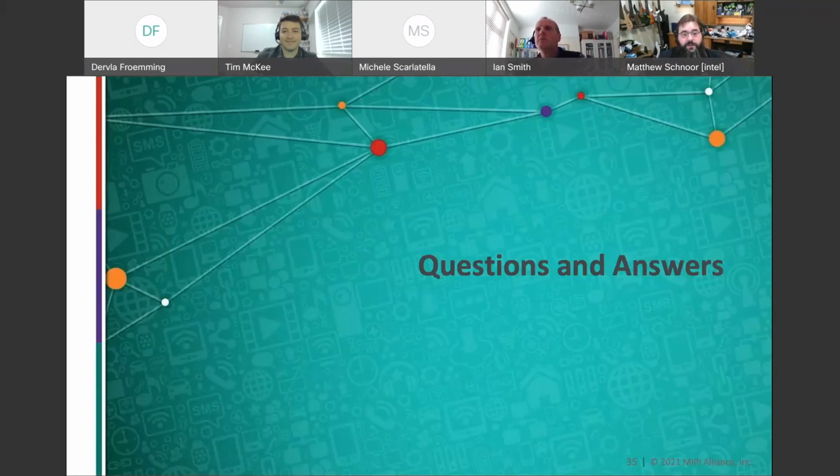Yeah, absolutely. Reset action is a command that lets you configure what the target is going to do when you immediately use the target reset pattern after RSTACT. This is something we developed in I3C 1.1 and then clarified again in 1.1.1. You actually have some very fine-grained control over what part of the target is getting reset with the target reset pattern in the RSTACT CCC.